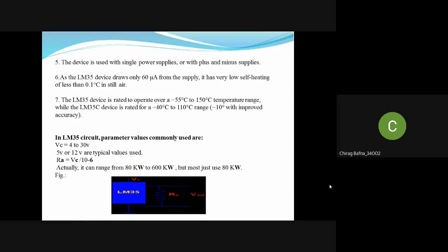Signal conditioning is widely used in the world of data acquisition. Most common transducers produce an output in the form of voltage, current, charge, capacitance, and resistance. We need to convert this signal to voltage in order to send it as input to an A to D converter.